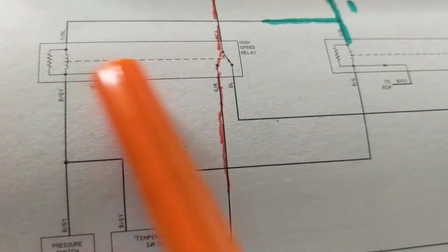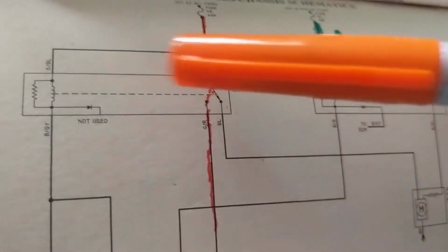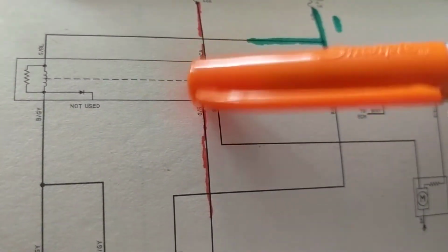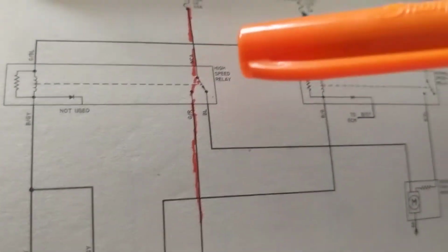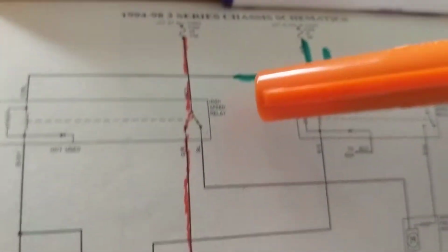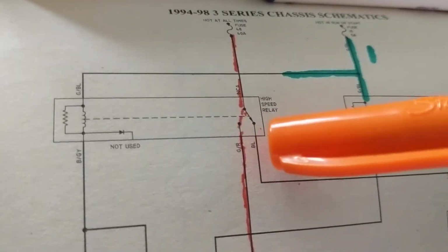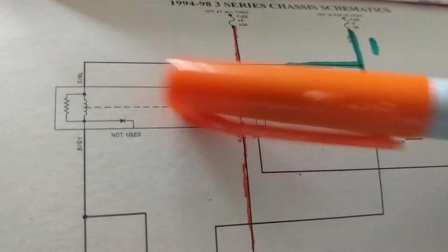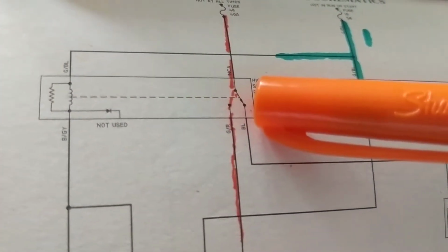As you see, the dotted line over here means at rest. When no current is flowing through this one over here, without the orange, it is in this position, at the rest position. And this is what people get confused about when I get emails. How do I know which position the switch is in? Well, while it's at rest position, meaning it's not being activated, it is in this position, which is drawn.